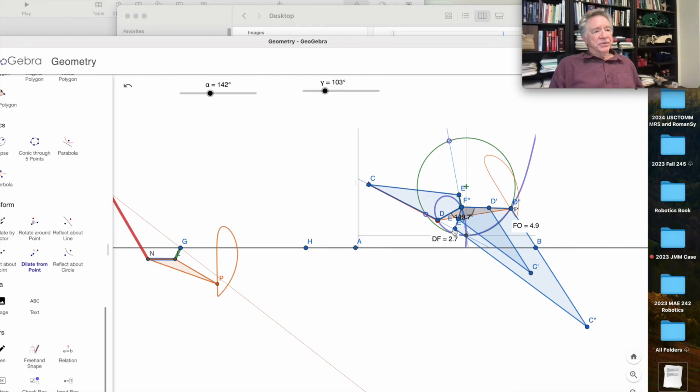What we've done, without maybe it being obvious, is construct this coupler link in a position so that it is attached to the input crank. So that sort of rotation and expanding thing has positioned this link that's scaled to the original 4-bar linkage in a particular way.